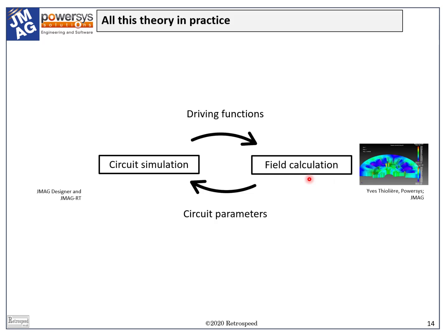There are, of course, second-order effects which I have not covered here. For example, the effect of spatial harmonics on the variation of Ld and Lq, and in the induction motor, the whole question of determining the rotor currents which are driven by electromagnetic induction and not by a current-controlled PWM inverter. Real windings are not sinusoidally distributed. In fact, it is impossible to make a truly sinusoidal winding distribution. For that reason, we must use Fourier series to perform a harmonic analysis of the actual winding and extract the fundamental space harmonic for purposes of the performance calculations.